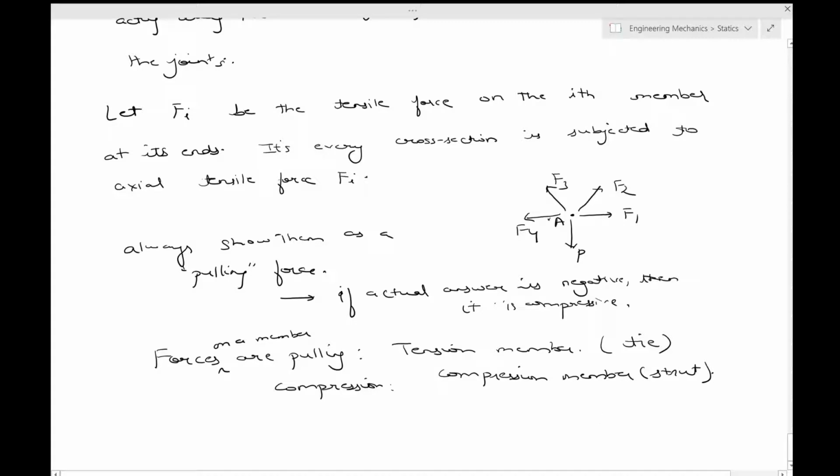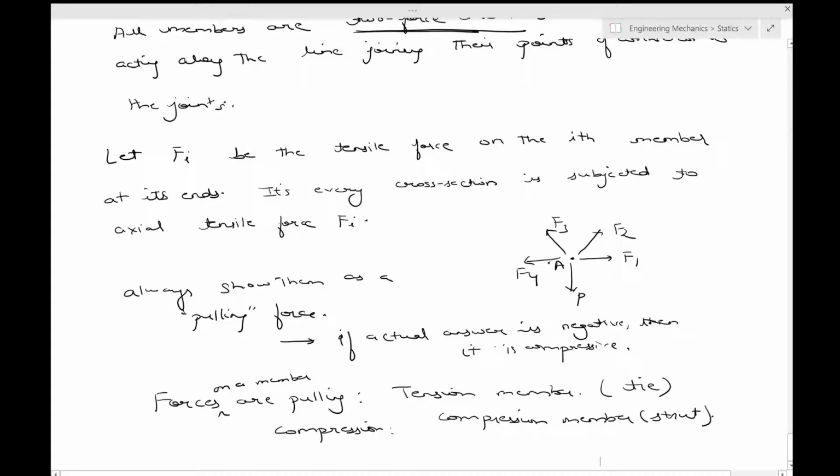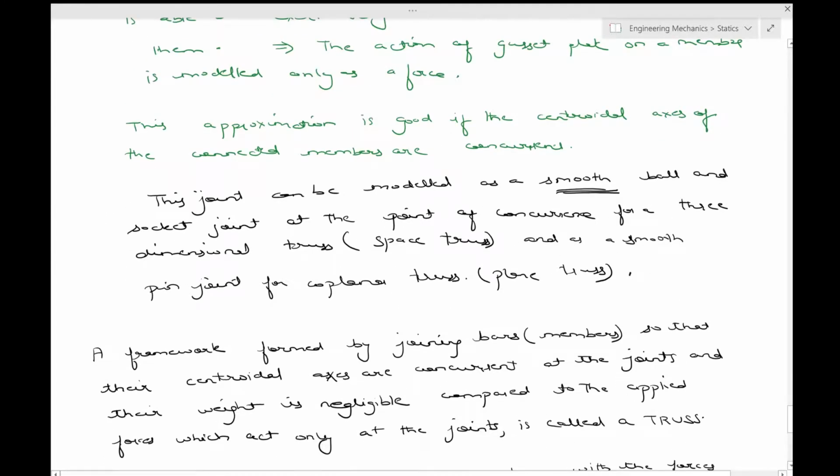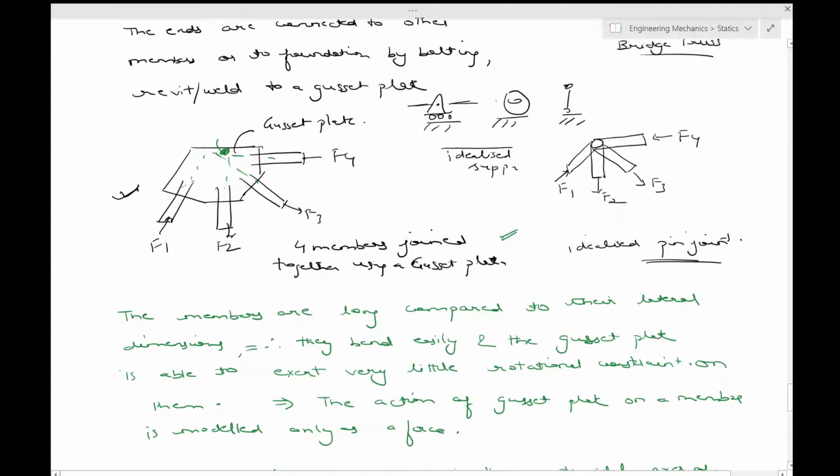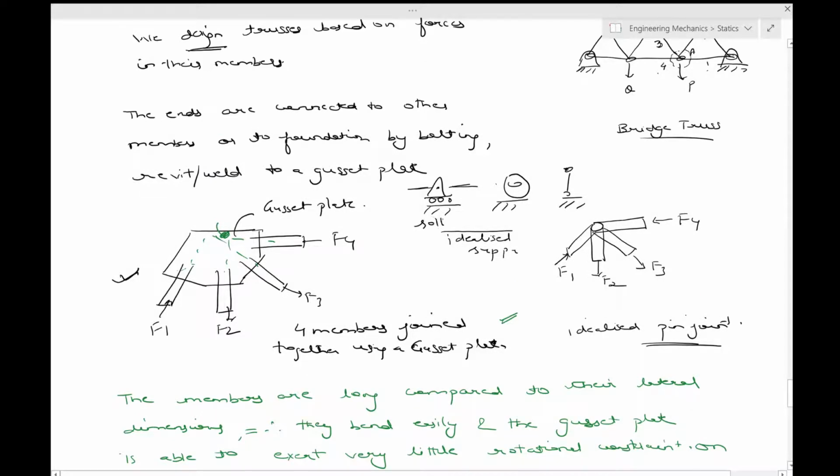Okay, so this should be a sort of a roller joint, a roller sort of constraint. It is a rocker, and this is a slip joint. The reason you require such supports is to allow a provision for contraction or expansion due to the temperature change at the support.